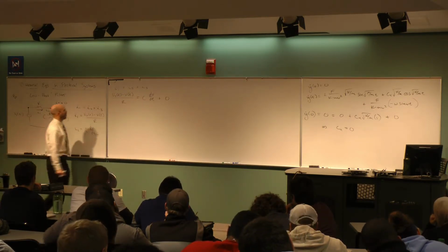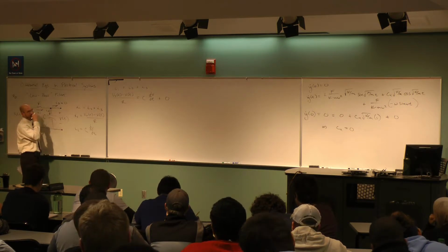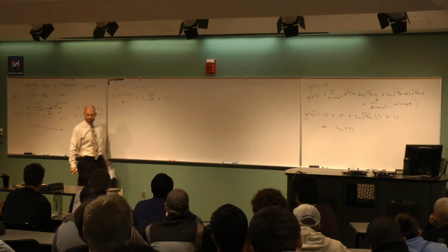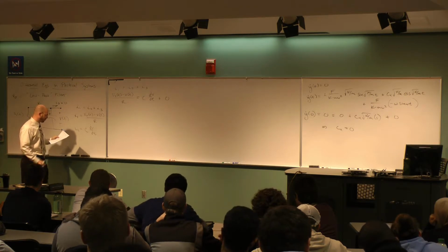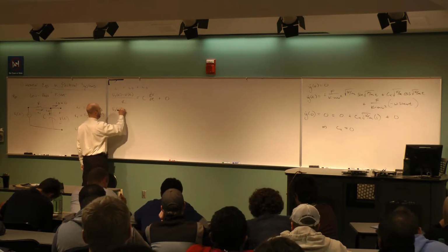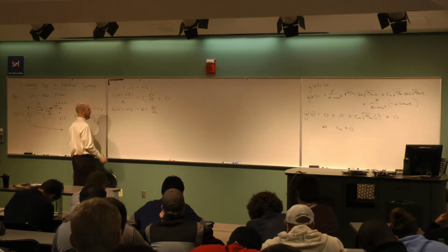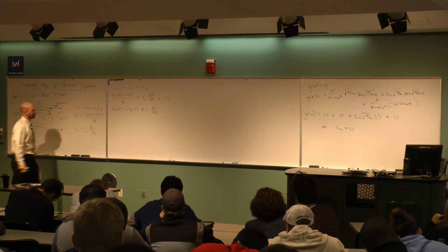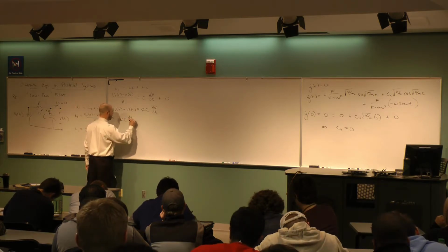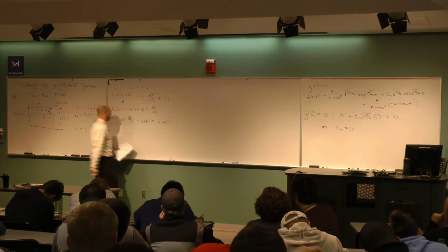And that's it. Vs of t is my source voltage. V of t is the output that I'm trying to measure. It looks like I have an equation here that's got V of t, and it also has the derivative dV/dt. So what I've got is a first order differential equation. The way I can arrange this, if I multiply all through by R, then I'll have Vs of t minus V of t is equal to R times C times dV/dt. If I put everything with V on the left and everything else on the right, then I really need to flip this around and write it as RC dV/dt plus V of t is equal to the source Vs of t.